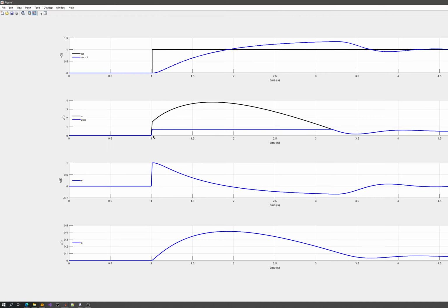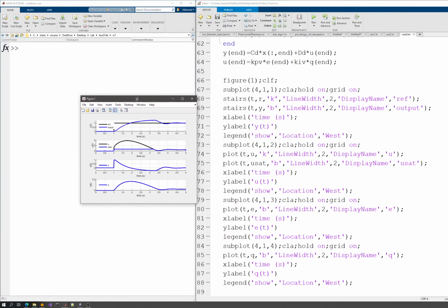How can I overcome this windup? Basically, there are two methods. You can switch off the integrator during the saturation. So if you're in the saturation area, you might just switch off the controller, and that's it. Much better response. So we have to switch this off. Or the other method is to feed the difference between the raw control signal, the control signal generated by the controller, and the saturated control signal, because that difference is used during the integral. Adjusting the value, the integrator should have a more accurate integral signal.